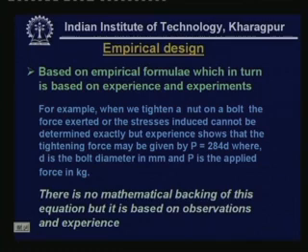When we tighten a nut on a bolt, the force exerted or the stresses induced are very difficult to find out exactly, but experience shows that the tightening force may be given by P equals 248 D, where D is the bolt diameter in millimeters and P is the applied force in kg. Surprisingly, there is no mathematical backing for this equation, but it is based on observations and experience.